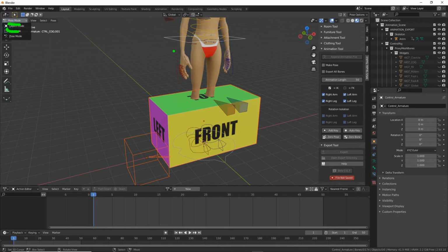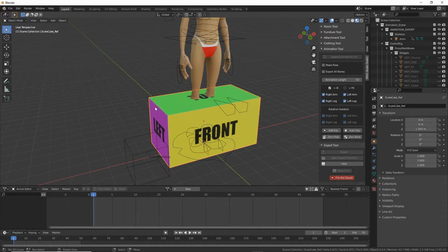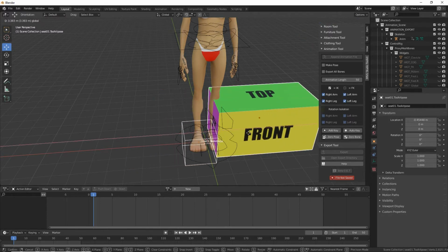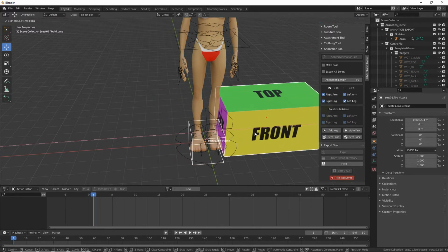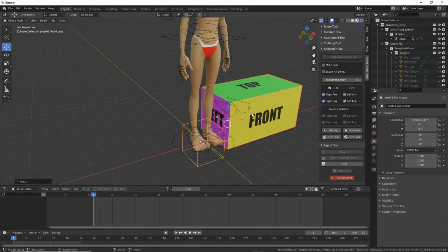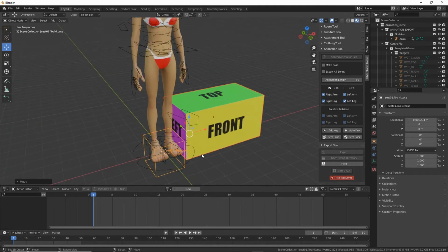We're in pose mode at the moment, which is why we can see all these special colored shapes. So drop into object mode, and then we can click, shift click our objects, use the widgets, not scale, so move, rotate, and just move them into position. Again, we're trying to align the origin point of the seat node to the origin of the avatar. So we're moving our furniture reference objects. That's all we need to do.